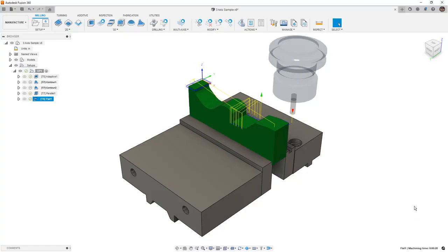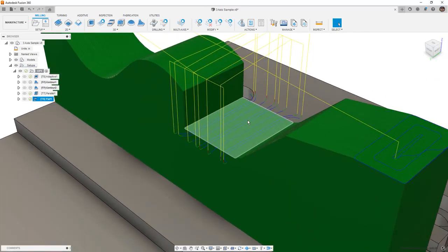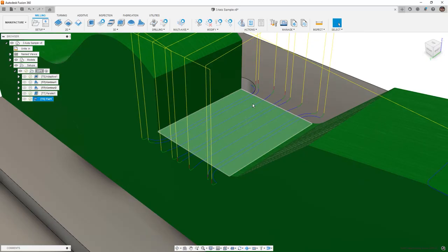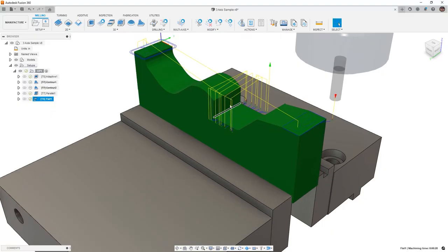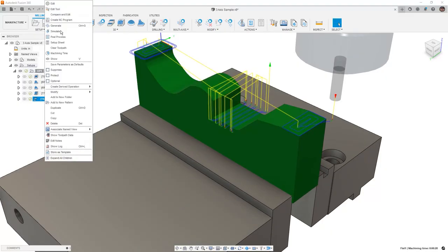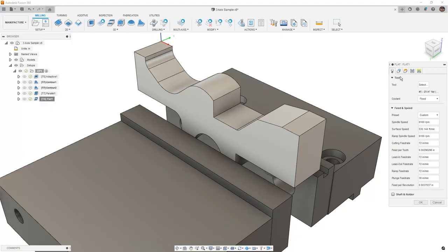I'm going to use F7 to bring back our toolpath preview, and we can see that it's cutting this top section here, as well as this bottom area. When we take a look at this toolpath, this looks like an efficient means to finishing off these flat areas and these walls, and it's something we could omit from previous toolpaths such as our parallel. But let's go back into our flat and let's take another look.